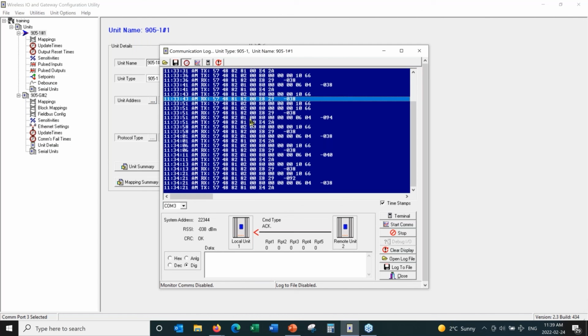The transmit goes out, an acknowledgement comes back. If radio communications fail, then we would see a bunch of transmits all in a row of the same message. So like in this case right here, it looks like we transmitted a message out once, never got the acknowledgement back, so after maybe 200 milliseconds, we sent the same message out again. And then finally, we got the acknowledgement back from the opposite radio.